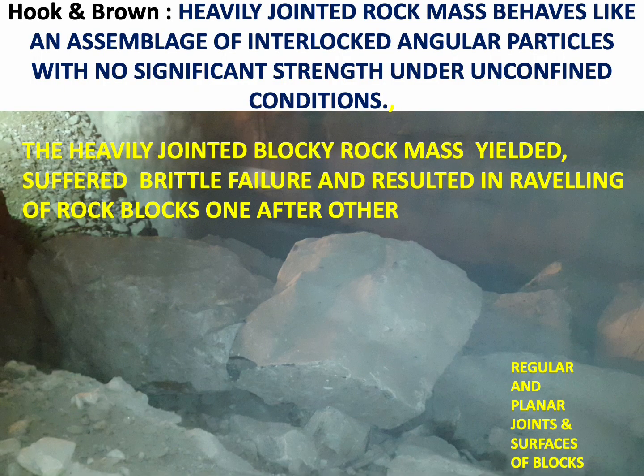Hoek and Brown mention that a heavily jointed rock mass behaves like an assemblage of interlocked angular particles with no significant strength under unconfined conditions. The heavily jointed blocky rock mass suffered brittle failure and resulted in raveling of rock blocks one after another.